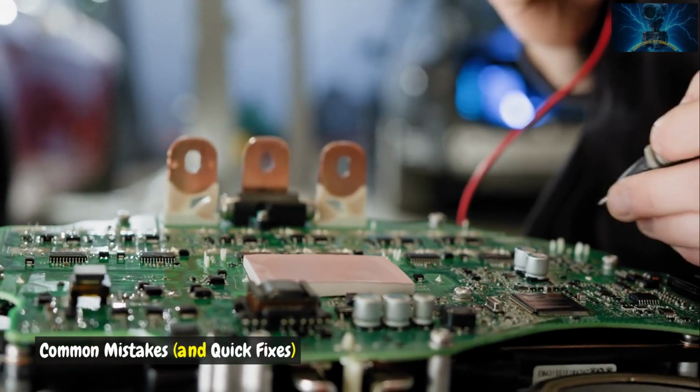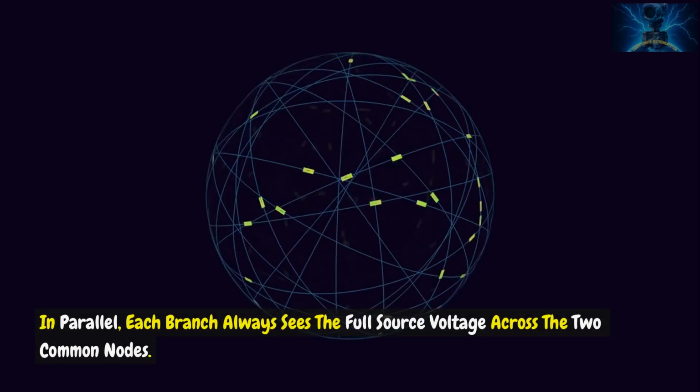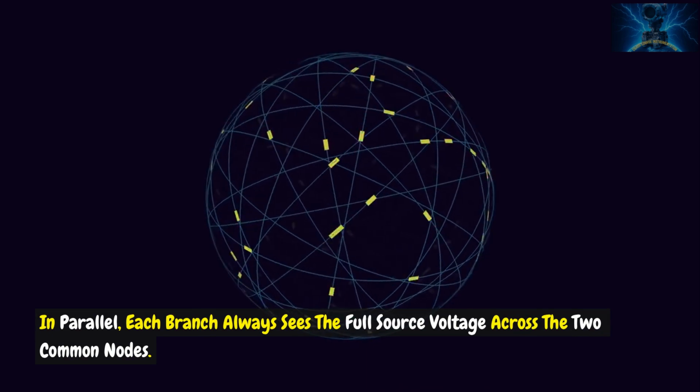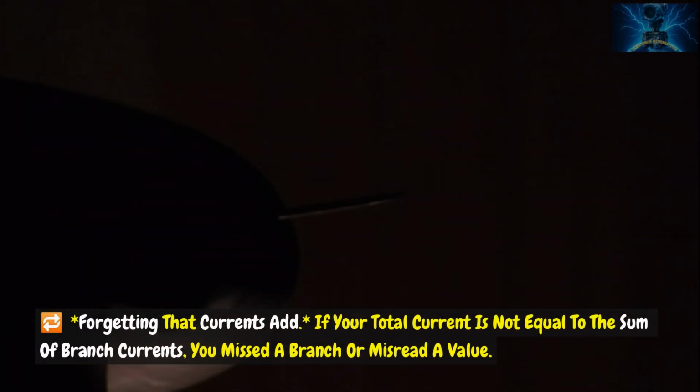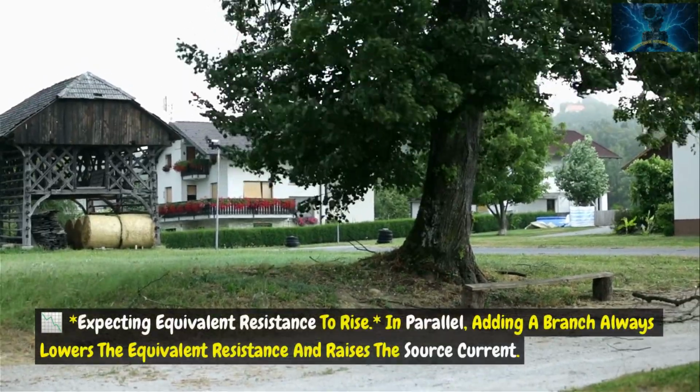Common mistakes and quick fixes. Thinking branch voltage changes. In parallel, each branch always sees the full source voltage across the two common nodes. Forgetting that currents add. If your total current is not equal to the sum of branch currents, you missed a branch or misread a value.